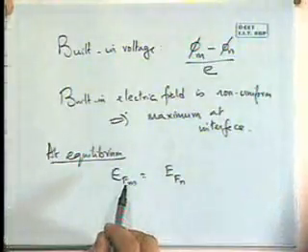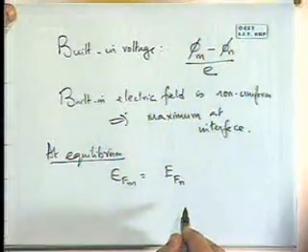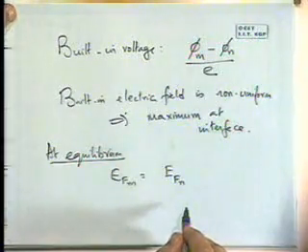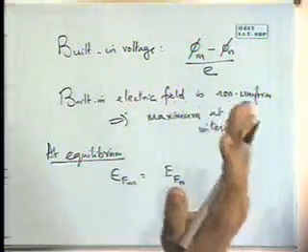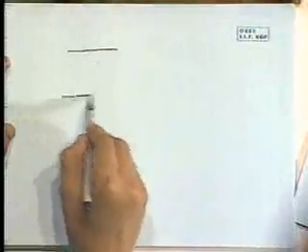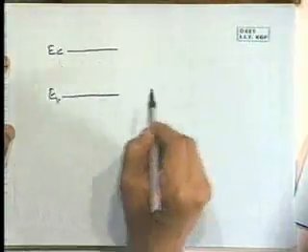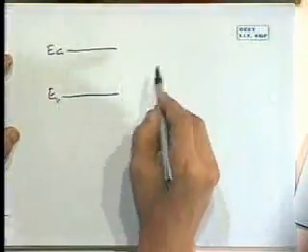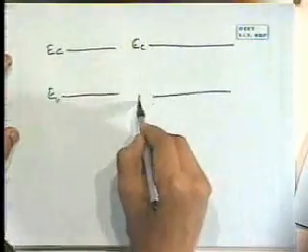Now we have to keep in mind that in the bulk of the semiconductor, nothing has changed. It is only in this small region close to the interface that we have experienced changes. What is the change that we have seen here? A layer has been created which has got fewer electrons. Now, when we think in terms of the carrier concentration N and with respect to the Fermi level, say if that is EC and that is EV, I'll draw two cases.